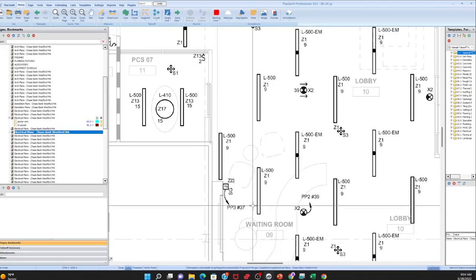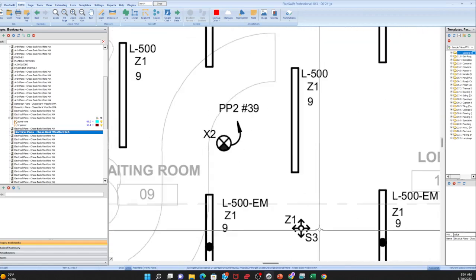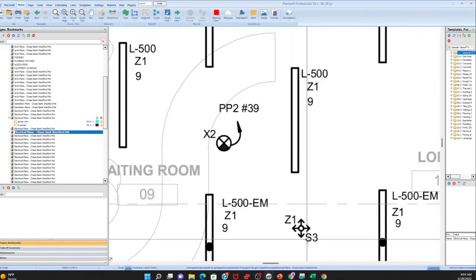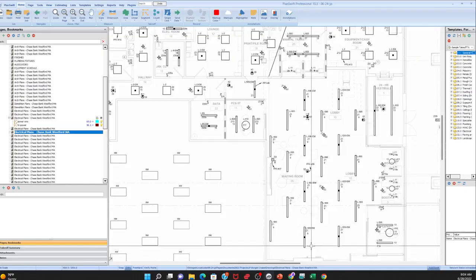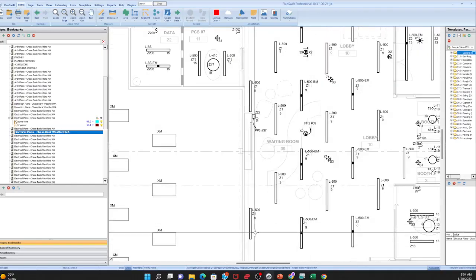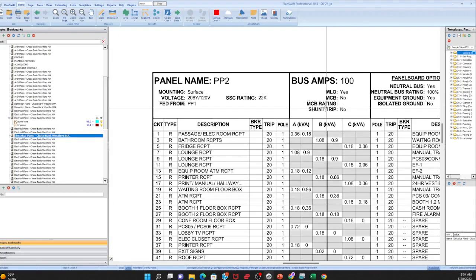First thing you're going to do is count all the different lights. Count all the occupancy sensors. Figure out what this is. This is some kind of occupancy sensor. So count all that stuff. And then use your imagination, because you know that it's telling the electrician all of these are connected together. And then I'm going to go to the panel, because one of these is the lighting control panel.